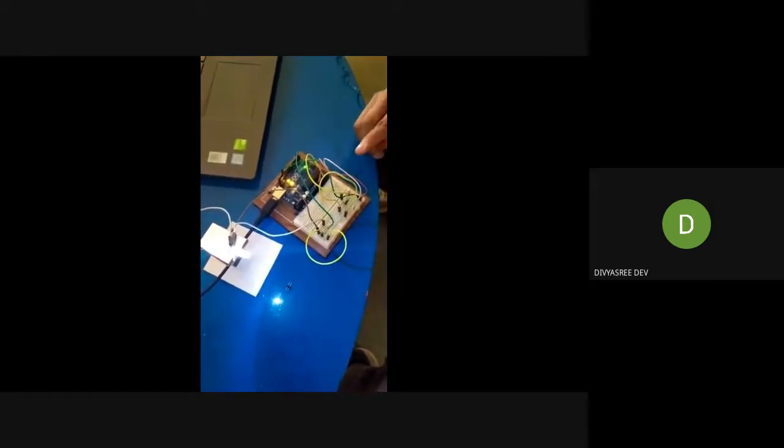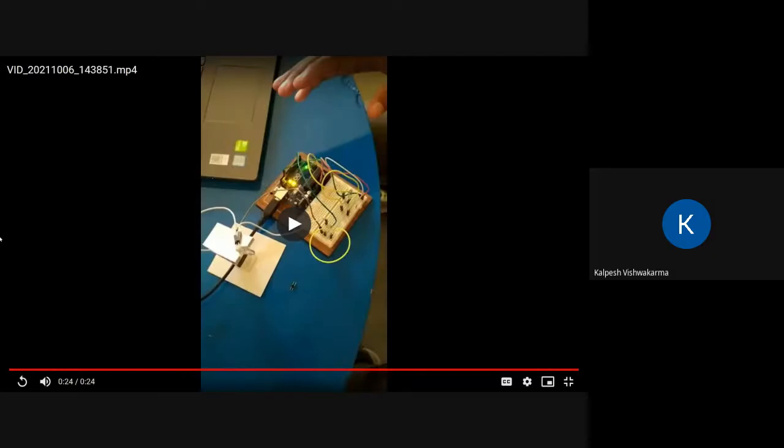Okay, so in this video we are covering the automated street light system using the LDR resistor. So in the circuit, basically once the light goes down, that means it becomes dark, the LED starts glowing. That is the purpose of automation. So as soon as I place my hand, the street light starts glowing. It has a basic implementation: when the analog input of the LDR goes below a certain value, it turns on the LED.